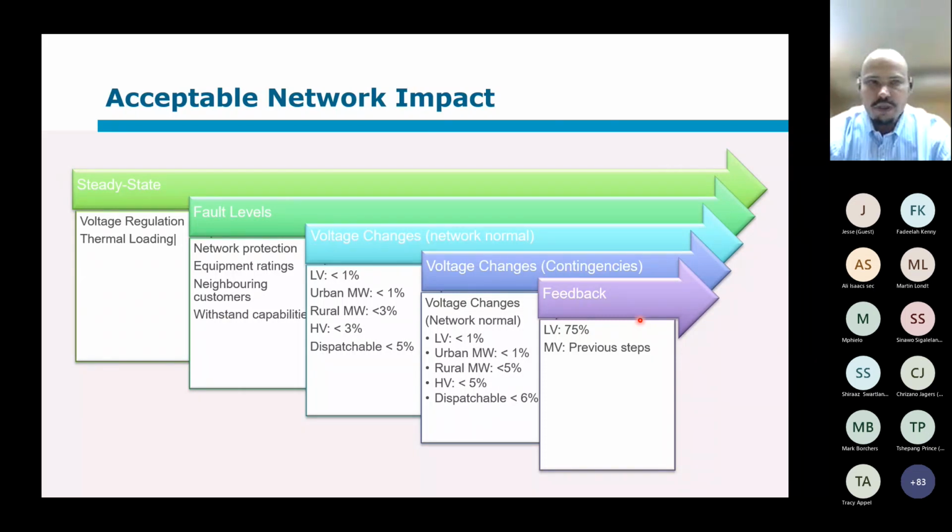At this point, I would rather say that keep it in mind in your internal policies that you start discussing with the suppliers of the transformers. What's the impact of harmonics? What can these transformers actually withstand? Because that wasn't part of the original specifications, the transformers aren't designed for it.